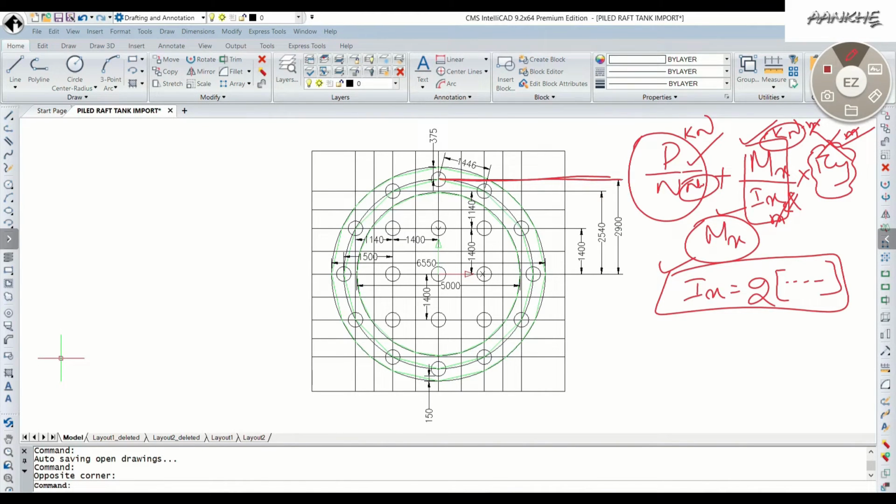This is as per the conventional analysis or rigid plate theory method, where we assume that the entire pile cap is a rigid element and it distributes the loads uniformly, right? Now let us come to the board, and we will be using the highest point R3, right?